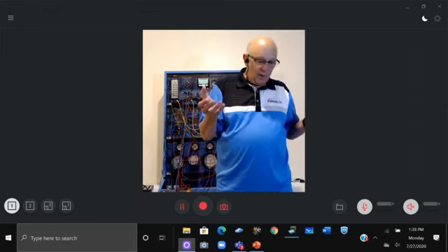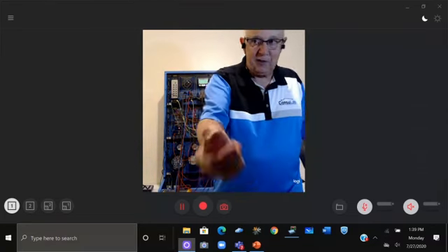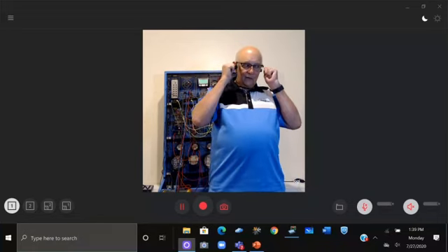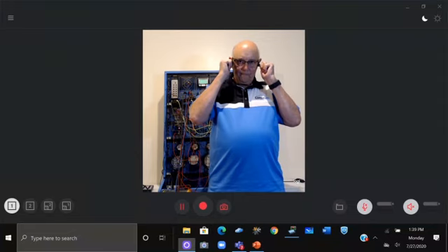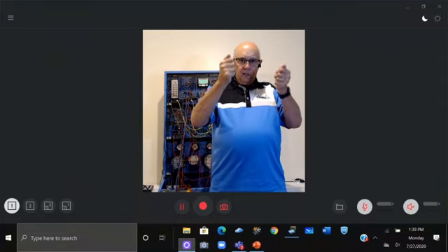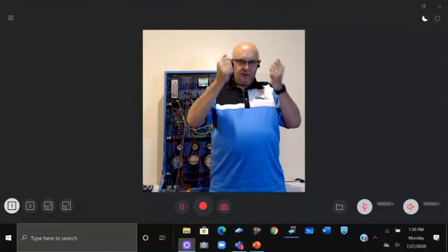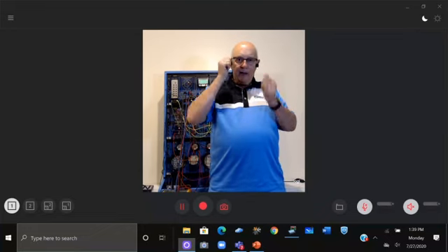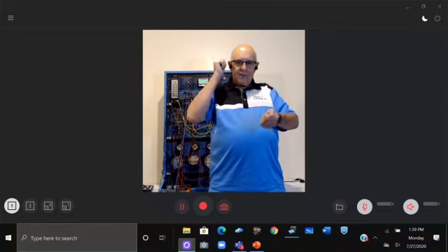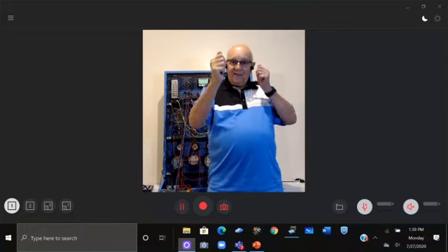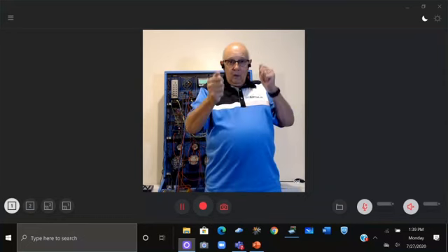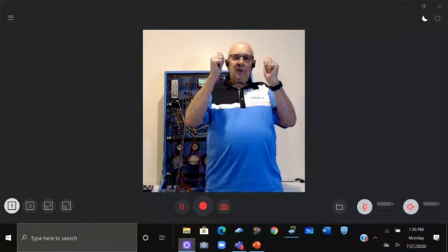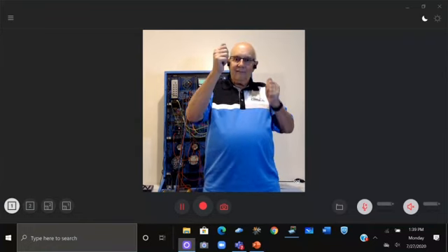I usually like to go up to the first person in the first row and say, "Can I borrow your cell phone?" I don't even have mine out here. But when you connect to an automobile with a scanner, what's happening is the high and low signals are doing this. Okay? When there's a bad module in it, it interrupts, and now all of a sudden they may follow one another, but they're not in sync with one another. And you're looking for them to be in sync, not follow.